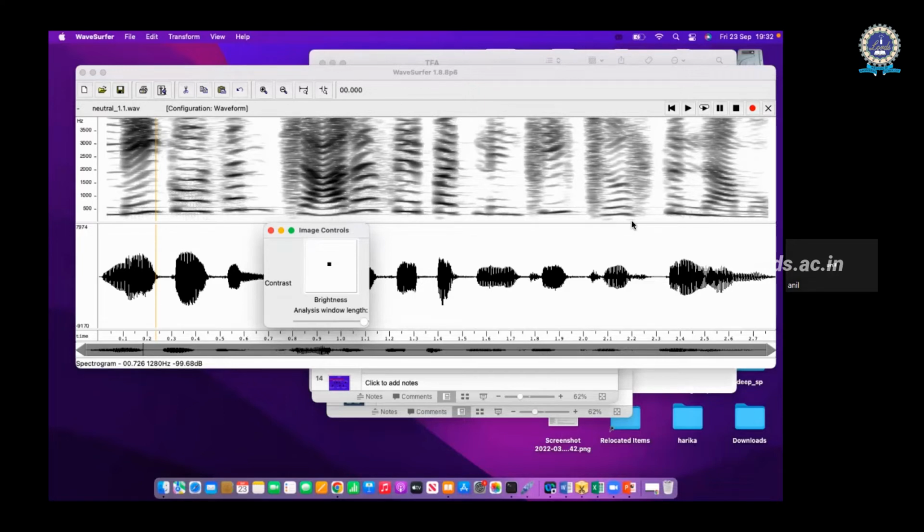So I have to choose the appropriate window, and also, if my signal is stationary within the window, the short-term Fourier transform works very well. Luckily in speech that happens. In speech I have shown you, right? There is some kind of stationarity. That stationarity changes, but there is some kind of stationarity. That's why the short-term Fourier transform perfectly suits speech.